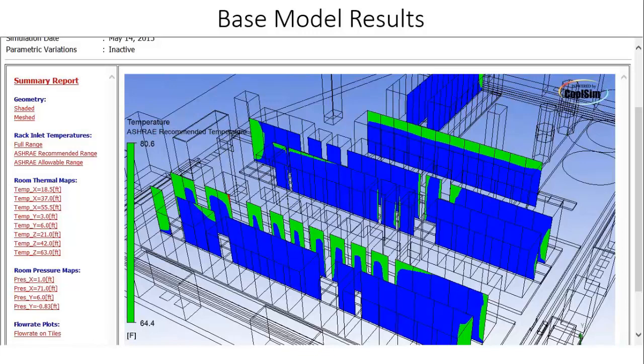So you see here, let me interrupt for just a sec. There's a question: what would you suggest the current and future expectation for power per square foot? Sure. And I think depending on the use, I go by a rule of thumb of an average of about 150 watts a square foot at this point. If you want to put that in a load per rack, anywhere from 3 to 10 kilowatts for normal operation.